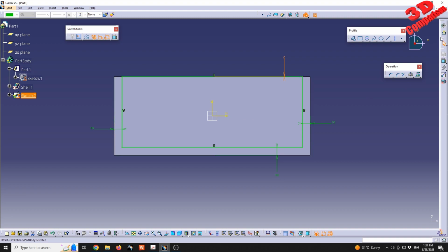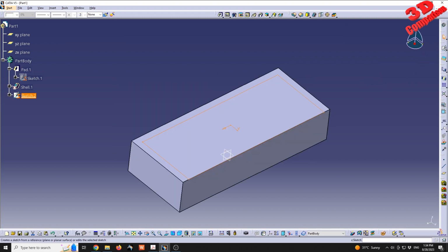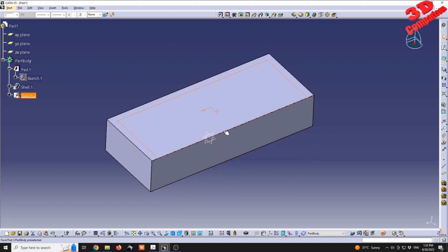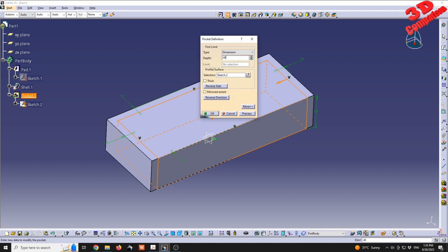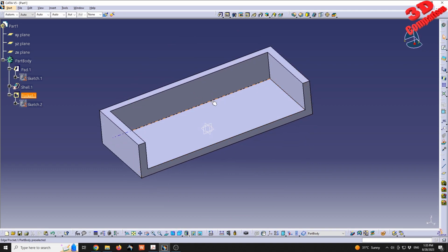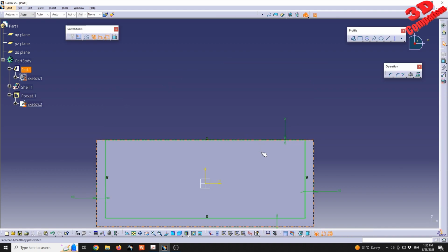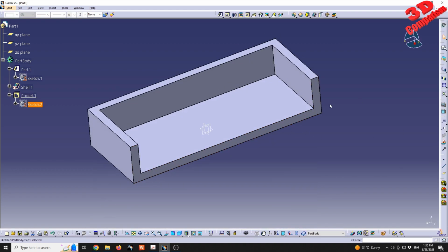When we position the sketch, we can go directly with sketch, or we can go with position sketch, because in this case we saw that the sketch was rotated. So keep that in mind when you're also drawing sketches within CATIA. And I will cut this on a distance of 40. So as we can see, we have the geometry exactly just like before with the shell, but now we can, let's say, more easily change those values if the design intent requires us to do that.